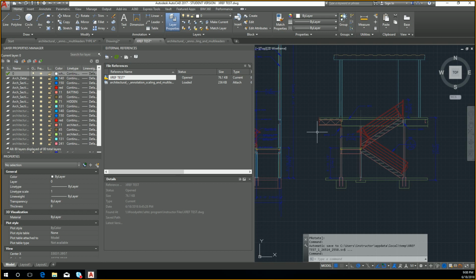That's how AutoCAD stops you from getting your blocks and references mixed up. On the other hand, if I'm in a drawing named BBB and I want to attach a file which is BBB as well, it doesn't allow you to do this, because it cannot reference itself; it would be a cyclical reference. AutoCAD will go crazy if you're allowed to do that.